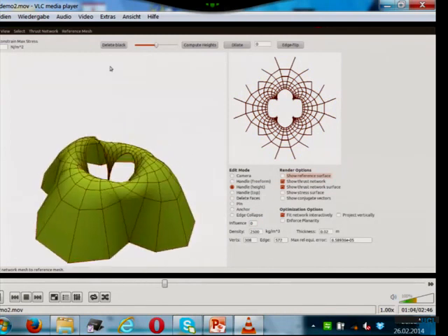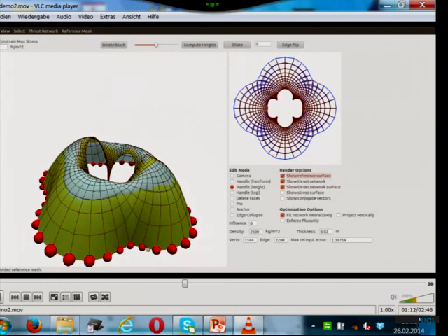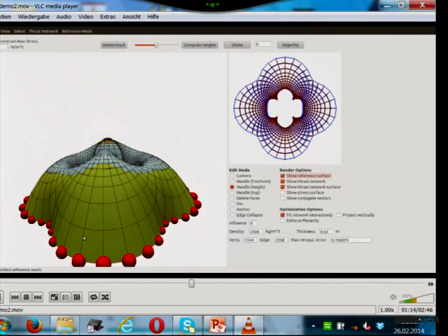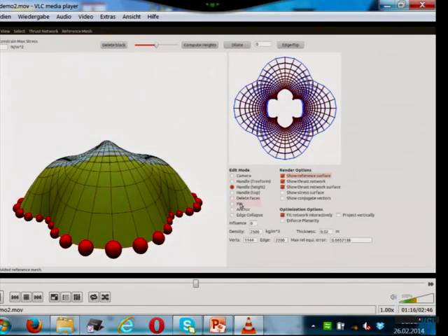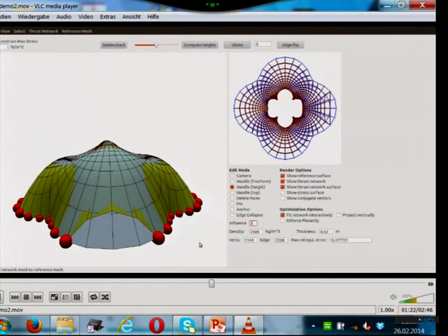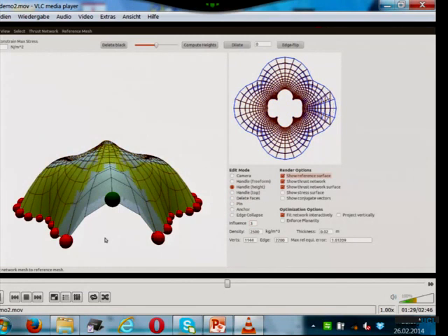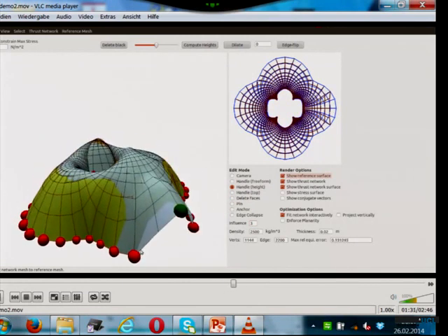What you see here, this black mesh, is a thrust network, and you see it's getting dangerous because it's too coarse. So you want to subdivide now, and of course then the shape should not change so much if you apply this green button, and really this happens. But then you have a better resolution, and then you can change the boundary conditions here, so no longer clamp it to the ground, and you can move it up and still make sure that it is self-supporting, so the surface has to lean back a little more.